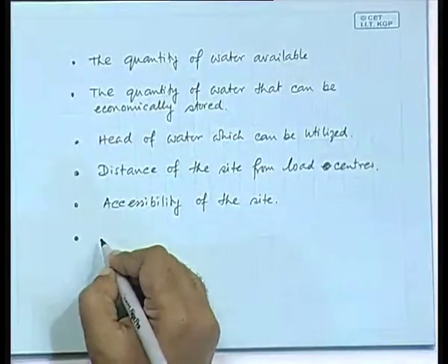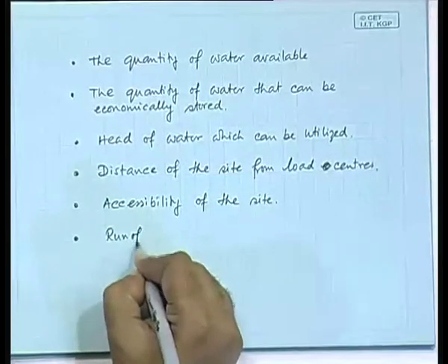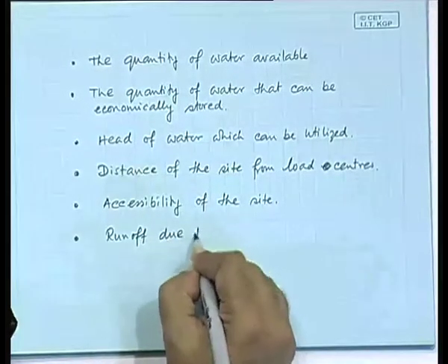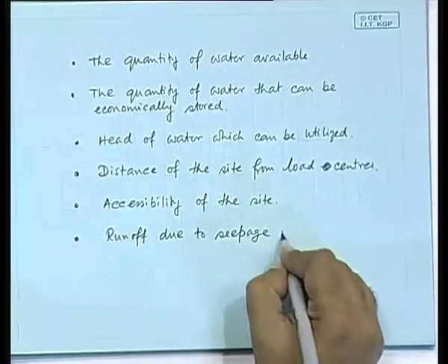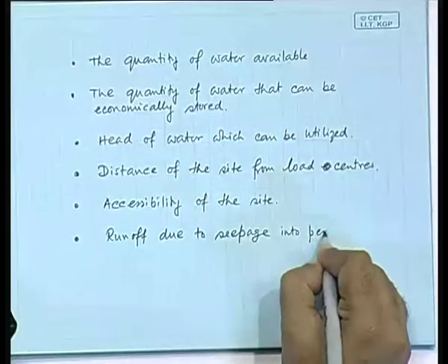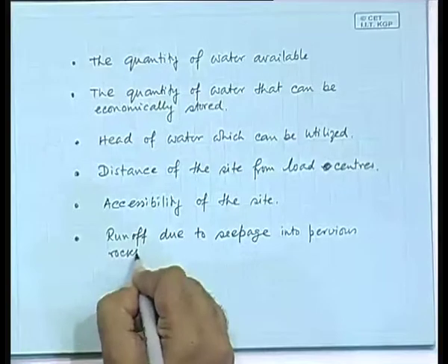Then you have to also consider the seepage. Imagine the situation where you have created a dam, but the rock underneath is very pervious, so that water does seep through, which means that the amount of water that is stored will not be there, it will seep through and go away.